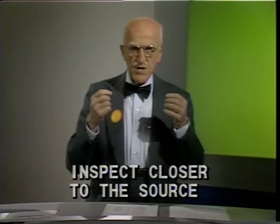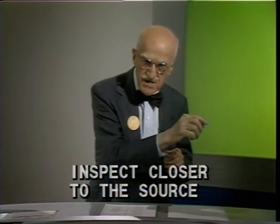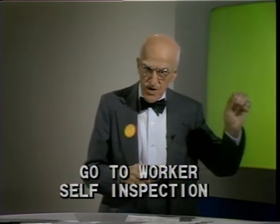Third, inspect closer to the source. Move the inspectors to where the product is made, rather than transporting the product to an inspection department location. Aside from cost reductions through improved logistics, the inspection becomes more precise due to improved traceability. Fourth, go to worker self-inspection. Under proper conditions, we can give workers the added job of product inspection. We then provide quality assurance through quality audits.